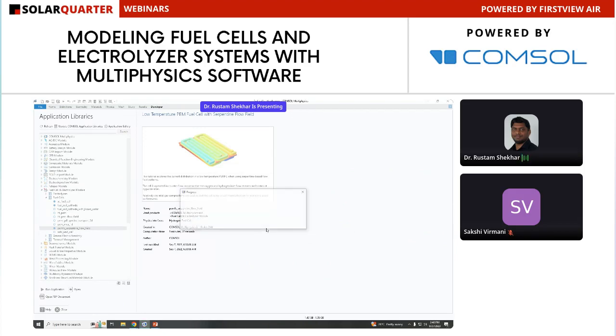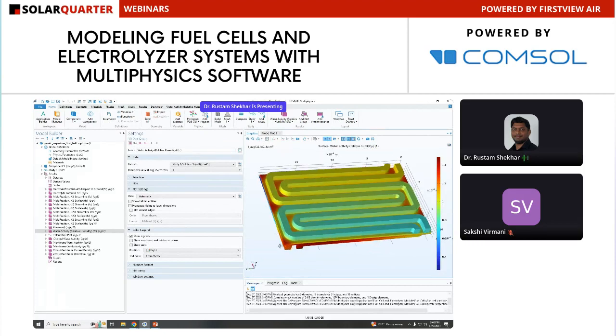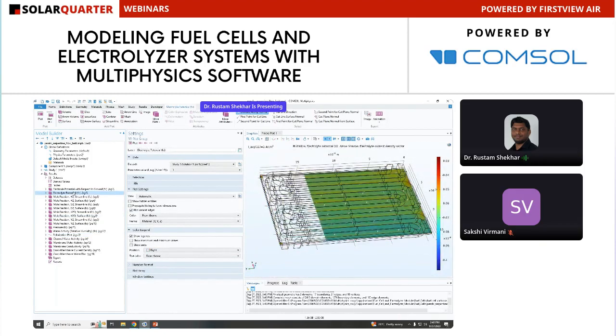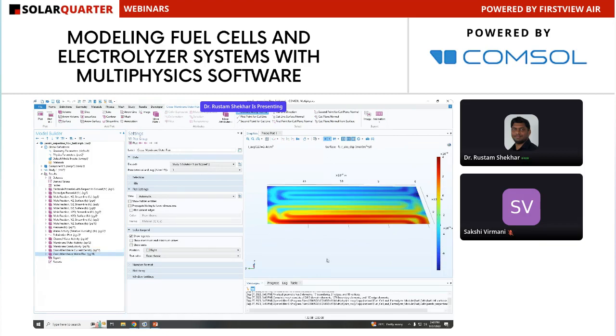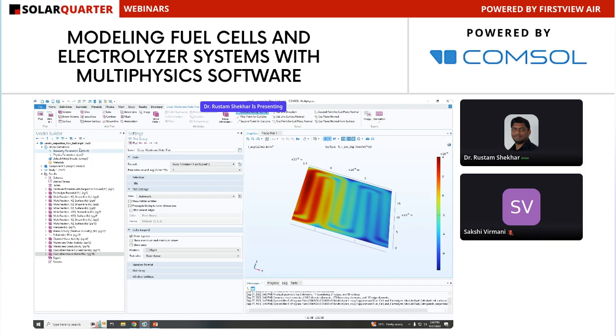So previously there was no flow field available. Now we have added one more detail to it, which is the flow field, and we can get the same polarization curves. We can get the flow profiles. We can get the electrochemical profile like electrolyte potential, and we can see the crossover of current densities and the water flux along the membrane. So these crossovers are now also part of the simulation.